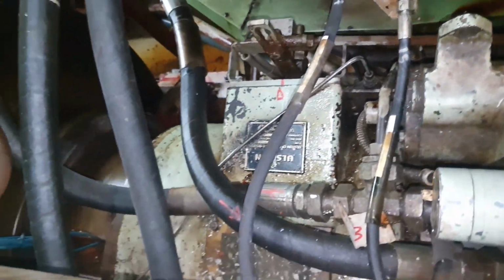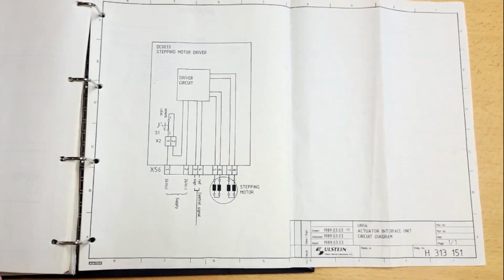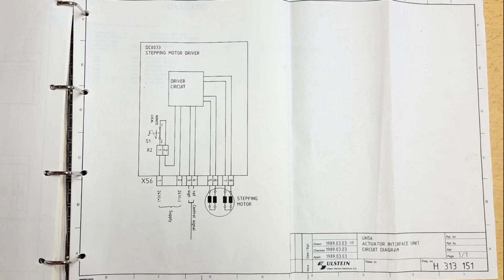Finally, the idea came up how to start the stepper motor in a different way. First, let's take a look at the schematic diagram. 4 wires supply power to the stepper motor. In normal mode, when the driver board does not receive a control signal, the motor winding is supplied with a direct current in order to fixate the rotor with a constant magnetic field, and it is no longer possible to rotate the shaft with the control wheel. Switch S1 is needed to remove power supply from the stepper driver board to unlock the shaft and thereby transfer the system to the local mode.